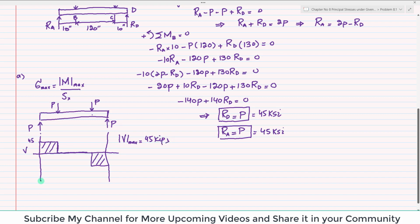Clear? Now we will move toward finding the bending moment diagram. So you can see from this point to this point, this is the shear force. Clear? And the area under this diagram will give you the moment. So this is 45 and this distance is 10 inch. Clear? So 45 into 10 will be 450. So you have to plot as per your scale. You have to draw the shear force and bending moment diagrams as per scale. Now you have proper knowledge and you can easily do it. So let's say this point is 450.